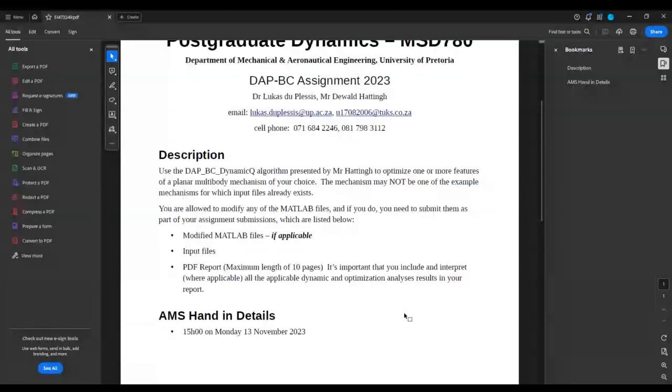All right, thanks. So you're going to give your initial design results, your optimum design results, and also your optimization history. How did the constraint values change? So the inequality and equality constraints, the lower and upper bounds, and your objective function. Dynamic Q is going to give you that as output at the end of your optimization. If we can get all of those results, I think you'll be sorted.